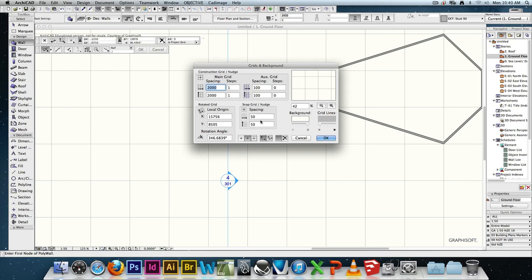Now the most powerful thing with CAD is its accuracy. Its biggest weakness is also its accuracy. Because if you just go and draw something up, this looks beautiful, and I've got pavers and amazing paths and all this sort of stuff, and then you start dimensioning it, all of a sudden you're going to start getting some pretty crazy dimensions. It's going to be like 1,372 millimeters long by 2,171 centimeters high, and it's just like, oh, this is terrible, and you'll get laughed off a working site.